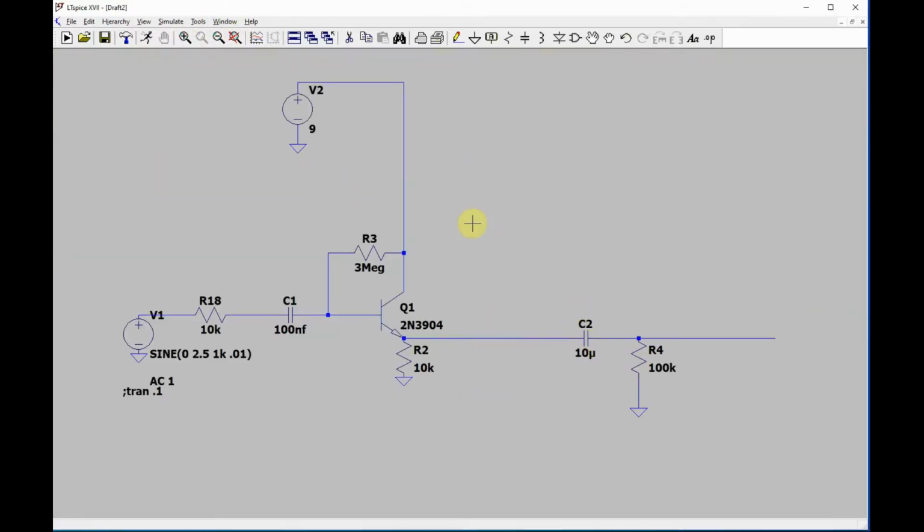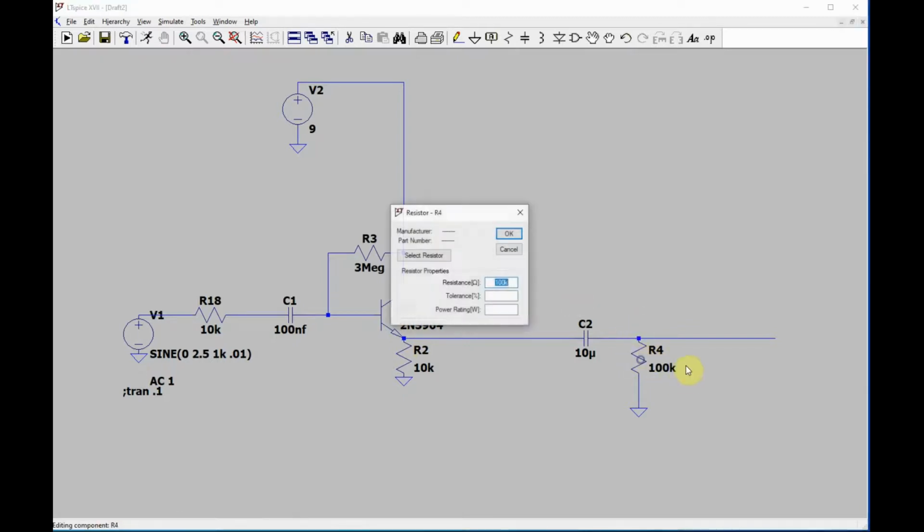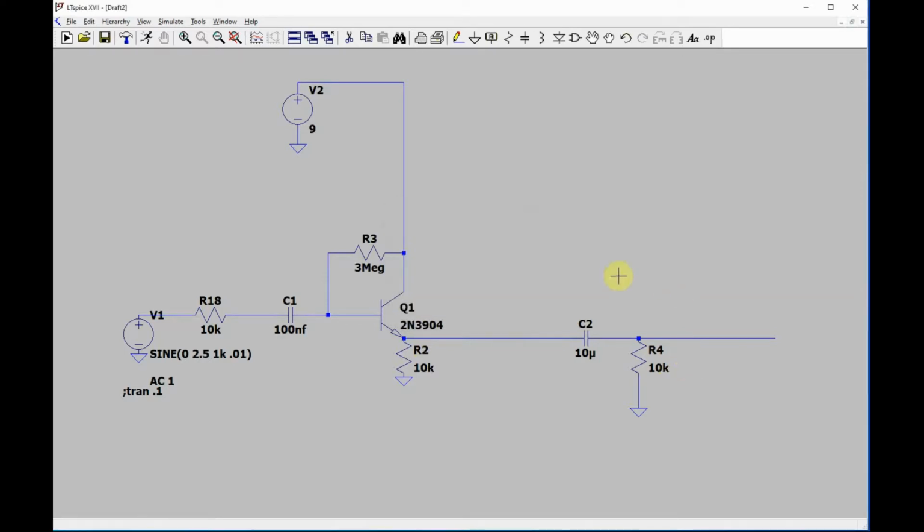Why am I showing you this? Well, we're saying this is like 30 ohm output impedance, and we're going into this, which is huge compared to 30 ohm. We're running into 100K. This is a little overkill here. You should be able to go into a lot less than that. But the problem with these, if it is a problem, at least you have to know about this.